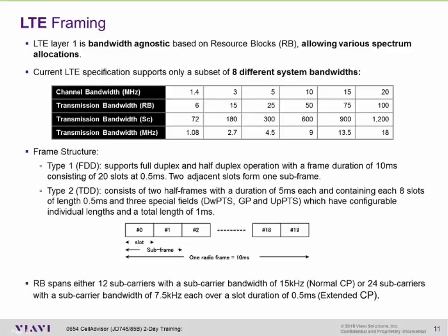We won't spend a lot of time going into frame structure, but needless to say, one radio frame is 10 milliseconds. Inside there you have 10 subframes, and each one of those subframes is divided into 2 slots. The test instrument has the ability to park on any one of those subframes, or it can continually rotate and monitor each subframe, which is referred to as frame testing. You will see in some of the demonstrations we give how it increments through those to evaluate each one of those subframes.